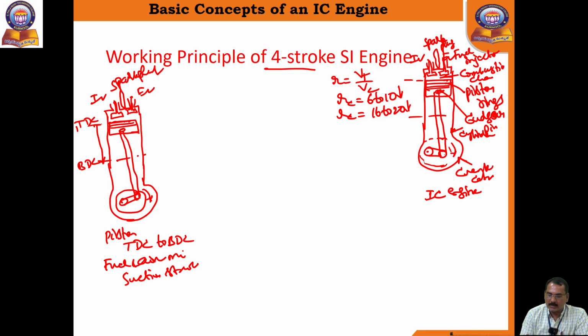Inlet valve opens, exhaust valve closes. And what about crank angle? Makes an angle 0 degrees to 180 degrees. This is happening during a suction stroke. Then coming to compression stroke, what happens?